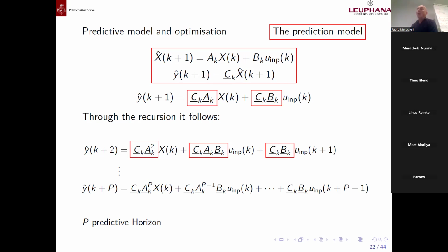If you use, for instance, Backward Euler, we have a totally different analysis model, because the Forward Euler is most used, even though not always the most effective. It's really a different way to represent the model, and also concerning stability and relative degrees, we have big differences. This means in the project we can consider together also different discretization methods. Let me show you again, then we will go ahead, the concept of the prediction.